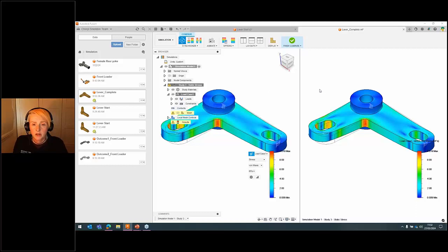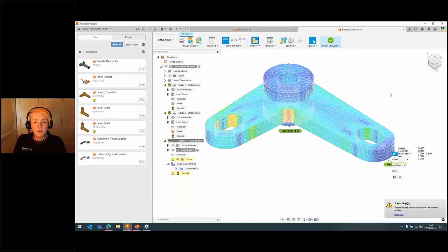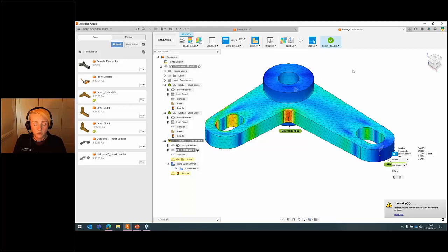So I'm going to show you another example of this that might be a bit better, and that's from the generative design environment. Generative design is basically a front-loaded process that allows you to add manufacturability constraints and criteria to your geometry before you run any sort of simulation on the part. And if anyone's done it before, you get these really organic shapes from generative design, which means you can produce parts that maybe the human mind would never think about doing.